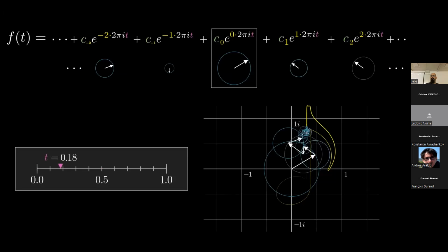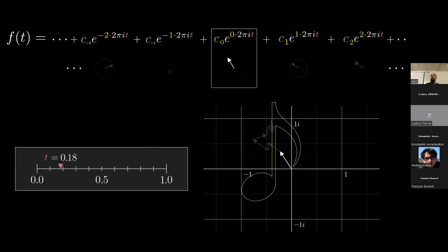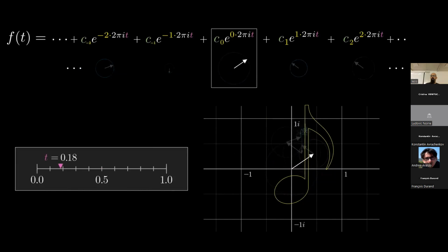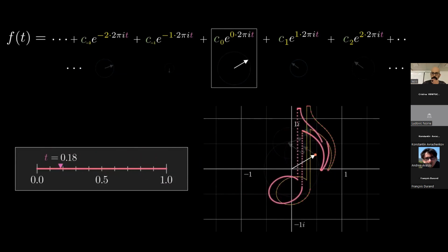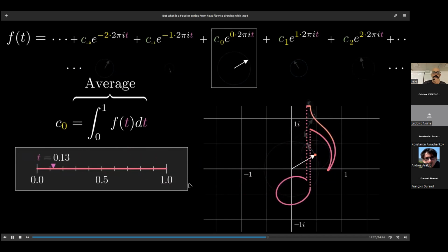So there is all the theory, all the explanation, and you can show that by tuning, for instance, c of 0, the initial parameter, you are just offsetting by the DC value, the constant value, and then the number of samples that you introduce can affect the quality of the reconstructed signal. And yes, so we are seeing all of those things.